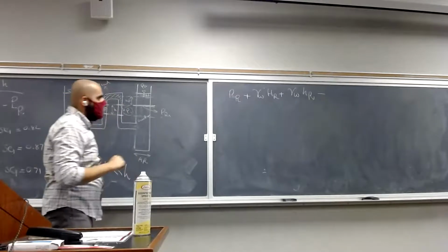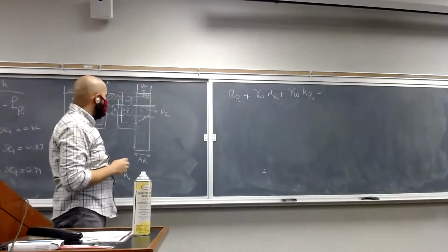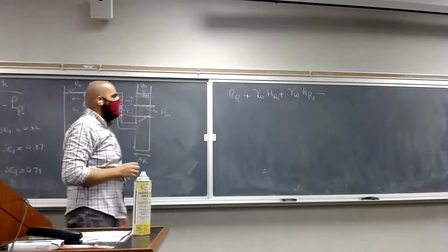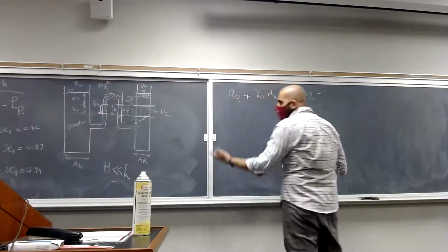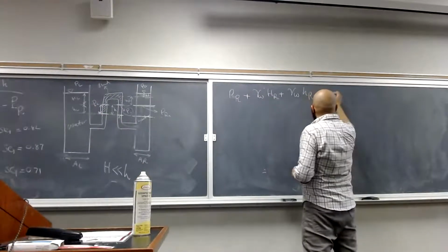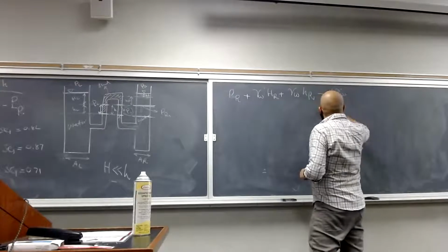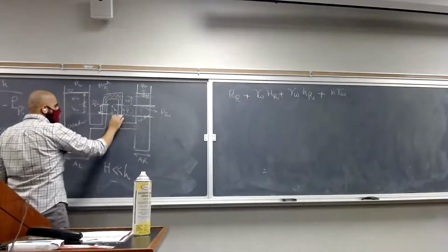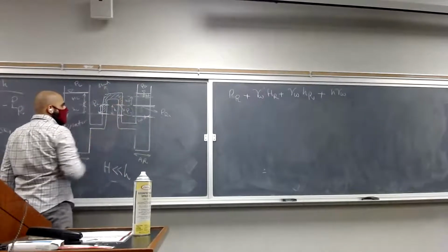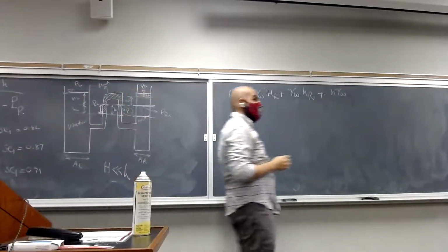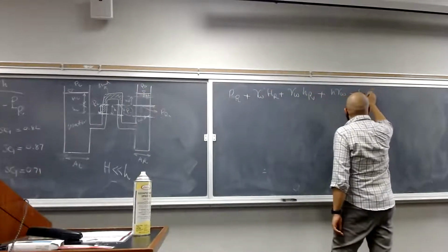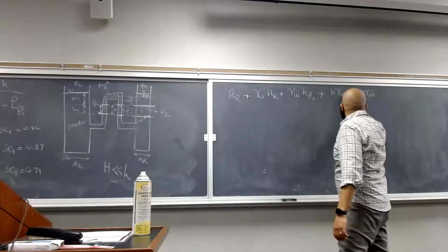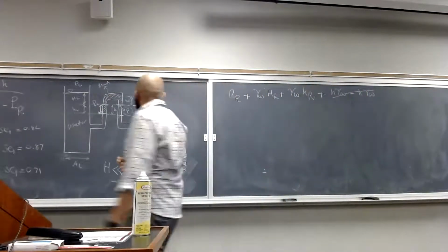What we could have done, let's actually do it completely. We want to find the pressure here and then move on to this location, right? So let's add that pressure here. It is going to be H gamma W, right? But then when you come to this part of the fluid, you are moving in this direction. So your pressure is going to reduce, minus H gamma W, right? So these two will cancel out. We don't need to include that.